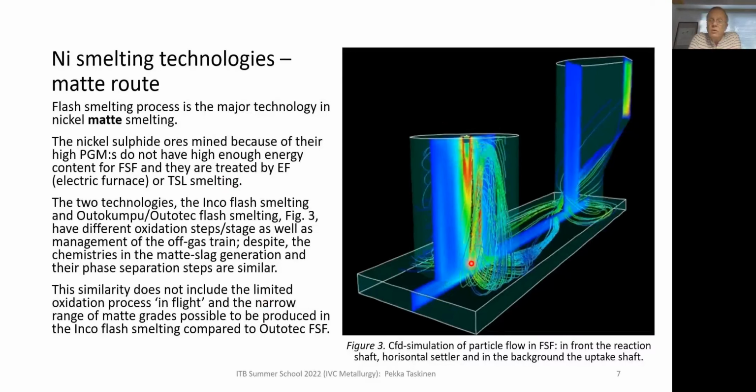So dimensions, temperatures, and gas flows are similar to corresponding copper smelting furnaces, but as I told you yesterday, the oxidation degrees of the matte are adjusted in the same way on both sides, copper and nickel smelting, based on the oxidation degree of the matte which is targeted, and the metal grades and fractions of sulfide materials in the feed mixture, by this oxygen coefficient variable explained yesterday.